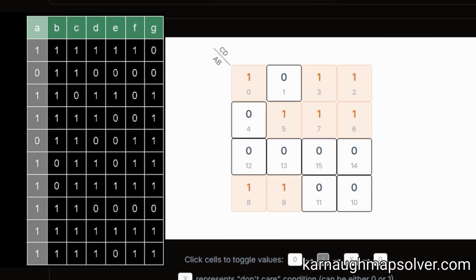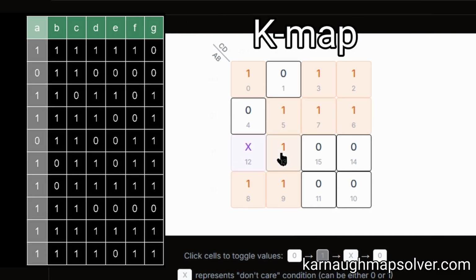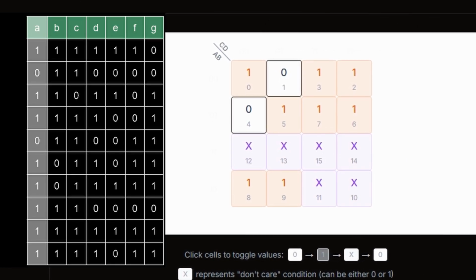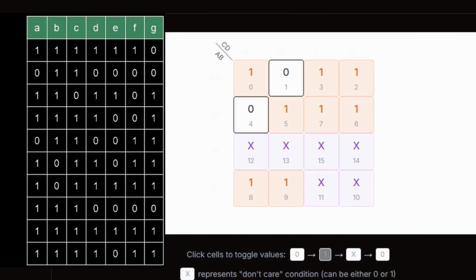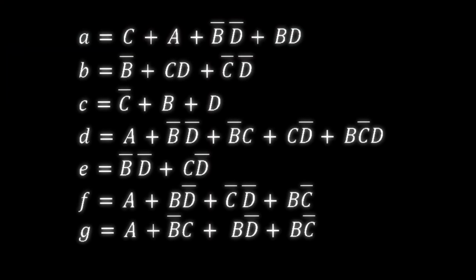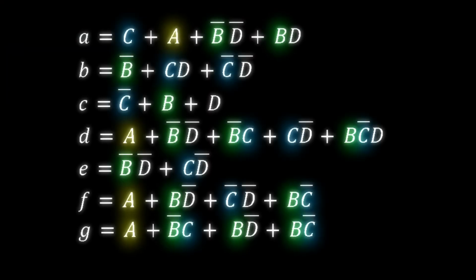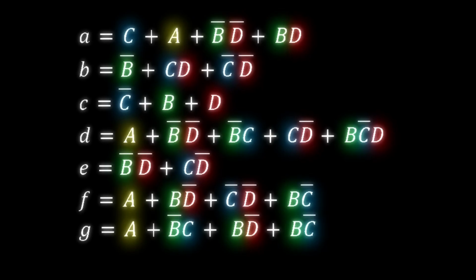Each segment now has a condition, and you can create a Boolean equation by using the Karnaugh map, or K-map for short. I use the K-map calculator because I'm lazy, and by following the order by the output for each segment, I got these equations. The outputs are determined by A, B, C, and D, which is the binary form for a desired number.